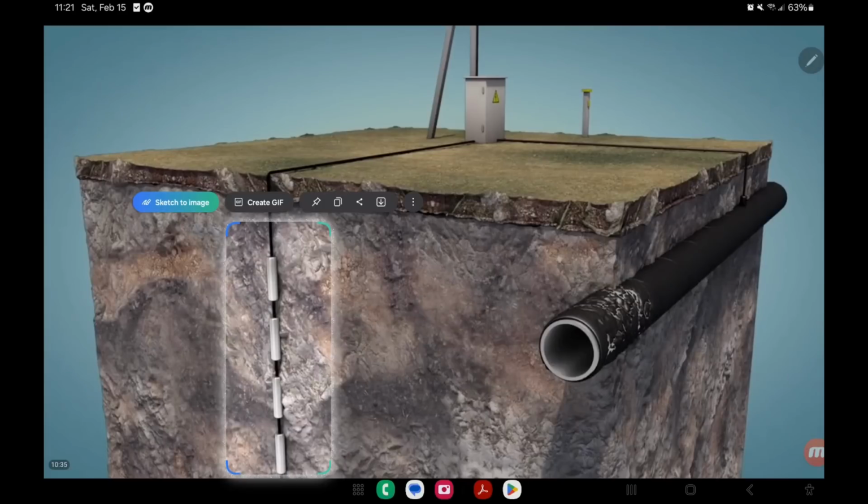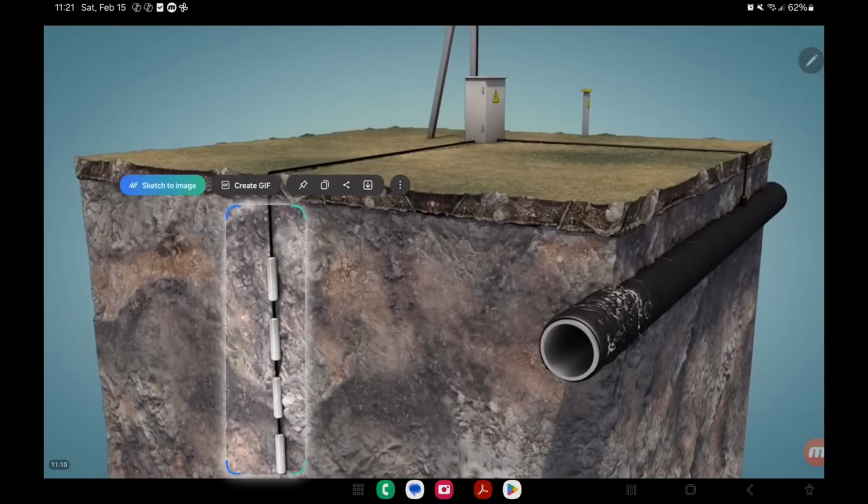In Venezuela, for example, the electrical code for houses, residential systems, I have seen many videos where they say that the code states that the grounding resistance for a house should be 15 ohms or 10 ohms or 5 ohms. Wow. When I see those values, to me that is too high for grounding. That's why we design based on these concepts, these premises.